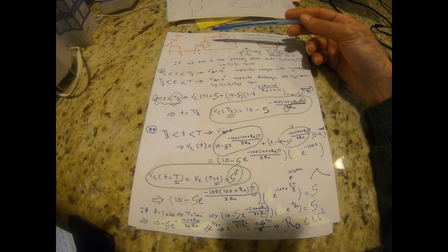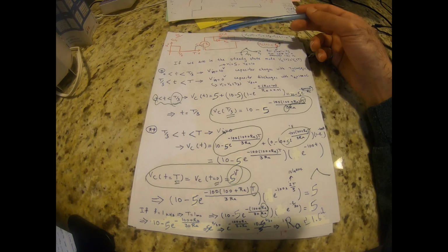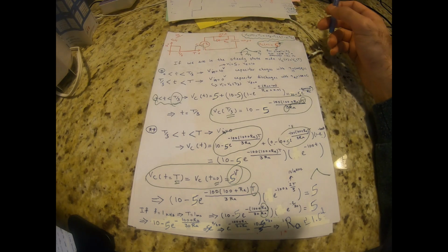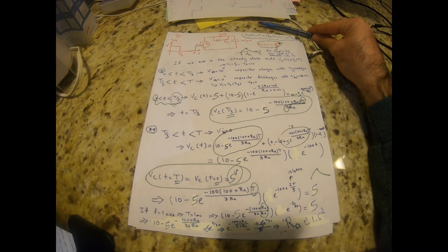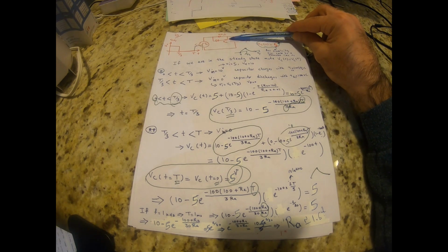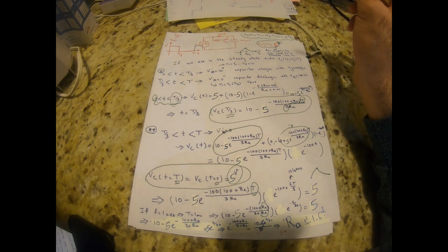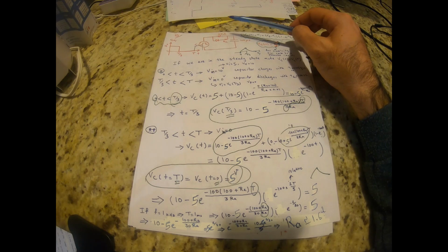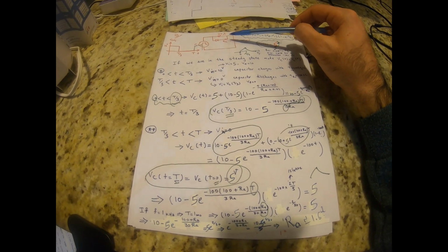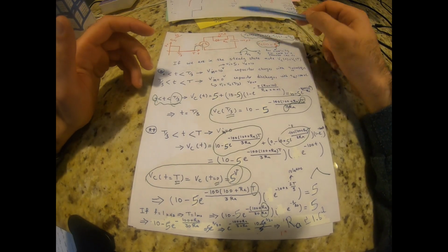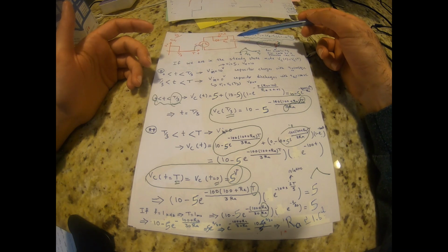I'm gonna repeat that. In the class we studied the concept of volt-second balance and amp-second balance without having any resistors, right? But if we have a circuit that is in the steady state and it has resistors and capacitors, we can still have the volt-second balance or amp-second balance for this case.